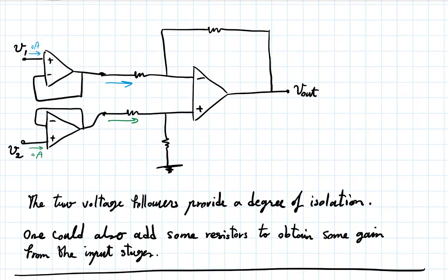One other thing I wanted to emphasize here, and we've talked about this before, is the modularity of a lot of these circuits that we are talking about. So a voltage follower, we could just now take it as a module, put it in front of a difference amplifier. So we are cascading op-amps. And the reason for that is, as you saw, the output of the first op-amp could essentially accommodate anything that was needed in the input of the second op-amp. It was because the output of the first op-amp could provide any current, because it had zero output resistance.